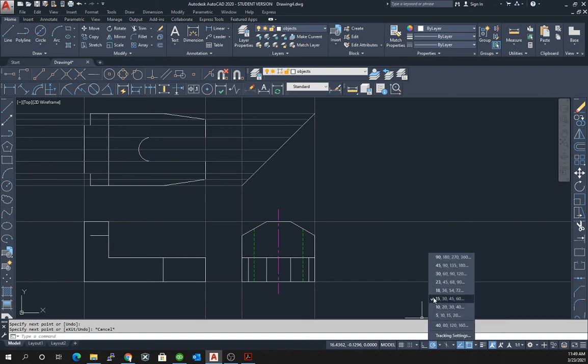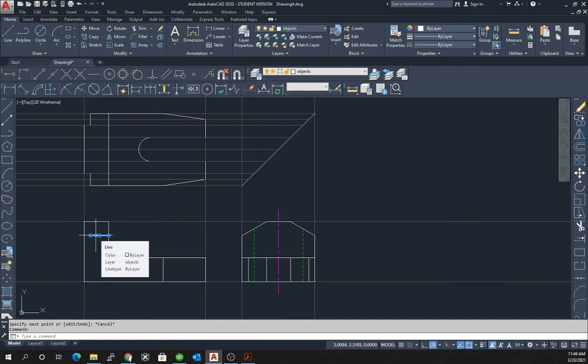And in fact, I'm going to turn off these angles first, because we don't need those angles, and those were adding a few extra tracking lines that maybe made it a little more difficult to see. I'm going to delete that. So we start from here, we bring across our tracking line, we start our line here, and we come up to this corner, and we get a tracking line from that corner, and we bring it down to here, to the point where we have a horizontal line, and then we hit our mouse button to stop the line, or to draw the corner, and then we hit escape.